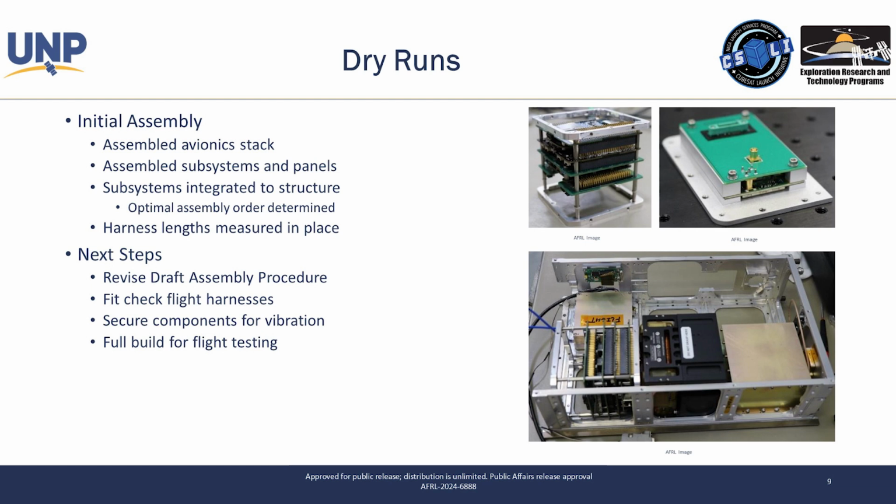And so every component needs to be secured so it can't oscillate, resonate, and break. Often that involves adhesives, which, when I said design for assembly and disassembly, are really hard to disassemble, though not impossible. Loctite, locking fasteners, things that are designed to be permanent, but often we want to be able to undo. And that's a very delicate balance.